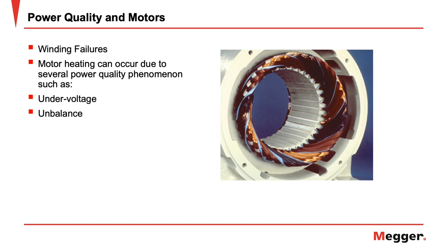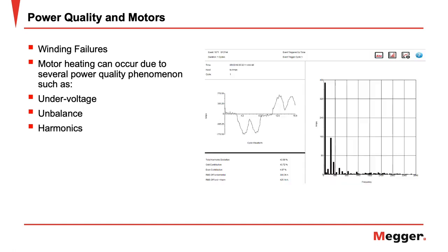Unbalance. Just a 1% unbalance in the phase voltage can lead to a 6 to 10% unbalance in phase current. This current unbalance will generate unbalanced heating effects in the coils. This leads to uneven phase heating. Depending on the winding configuration, Y or delta, a phase or two respectively will be heated more than the others. This can lead to failure of these coils.